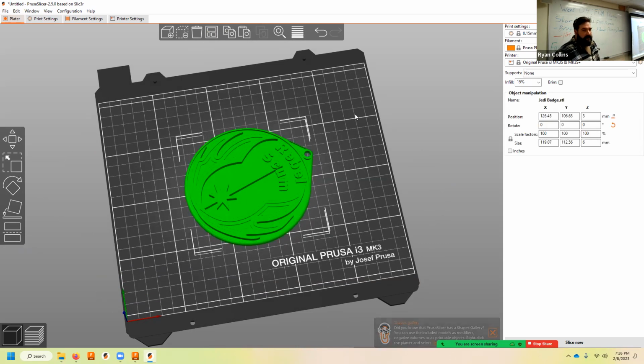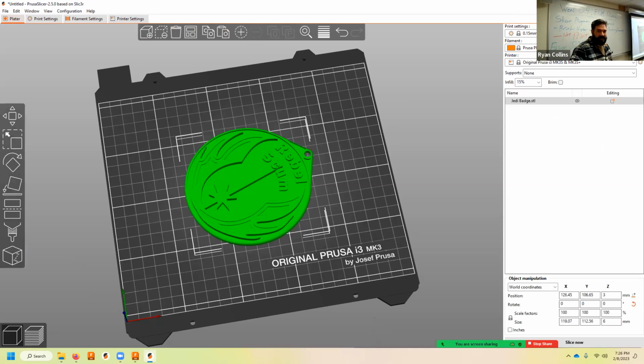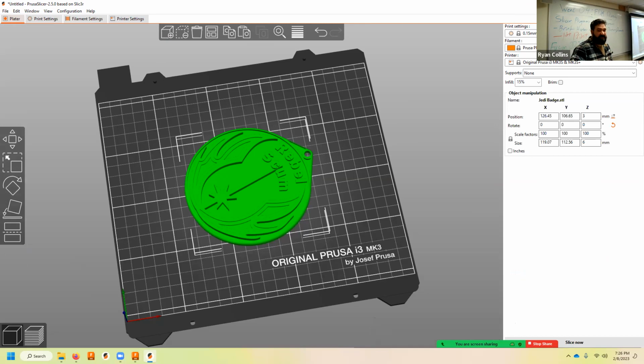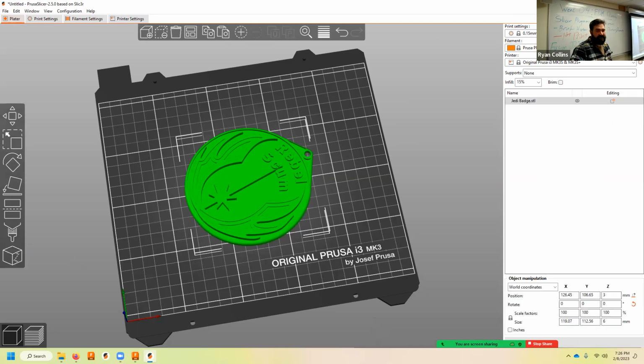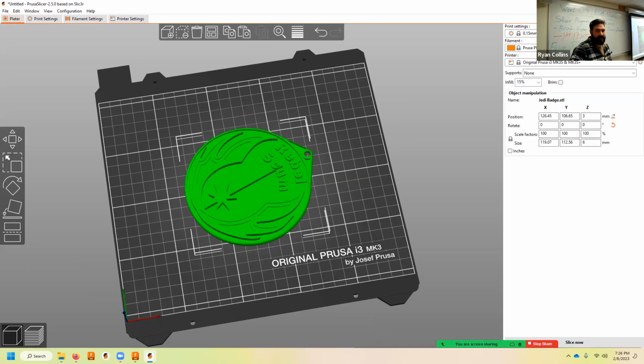All right. The other major options are, yes, you have tabs up here. It might be simpler if you have these other tabs on the right side. There's a simple setup, advanced, and expert. We'll just keep with simple or advanced, same diff. There's a few different options here. Basically, staying in the simple mode, cool. Cura has the same options. Main things you want to adjust, your print setting.